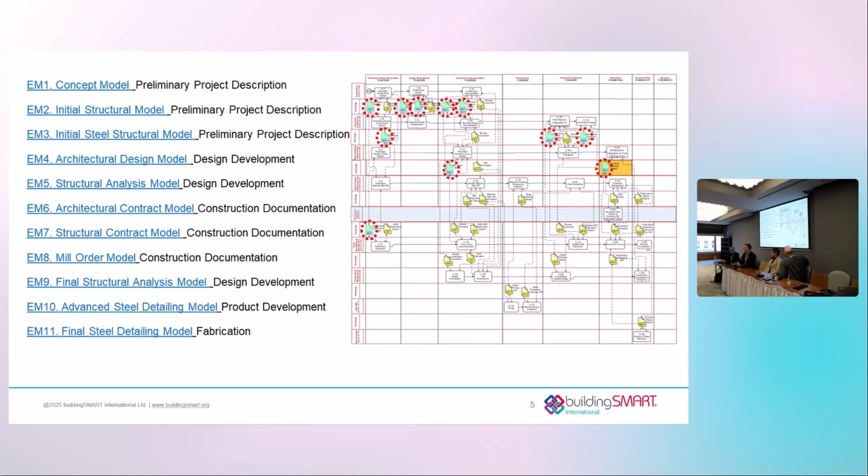We had found along the way, I think Andreas will probably talk about it, things that were as simple as bolt holes that seemed very obvious to us were not quite as easy in the previous version of IFC. So we are left trying to update for both IDS, I guess we can get into the specifics of what was in the MVD before, but left to both update for more current versions of IFC rather than 2.3, and that would allow us to cover some of the operations that were not covered before and have a more complete fabrication exchange.